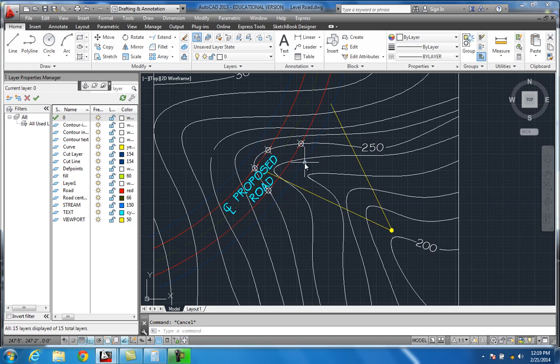And that line is going to represent our cut at the 260 foot contour. So there's 250, you go up one more 10 foot contour interval, that makes this line 260 foot elevation, and you sweep through here, and this line represents the 260 foot. Where those intersect will be your next point.